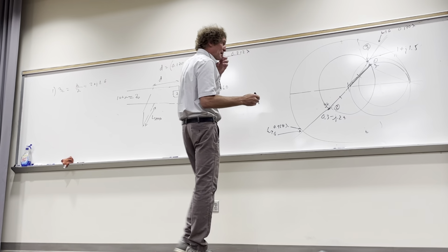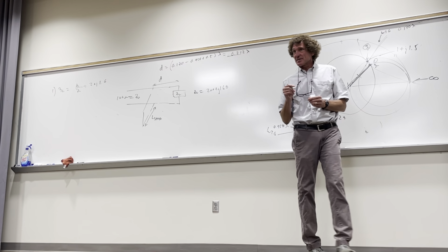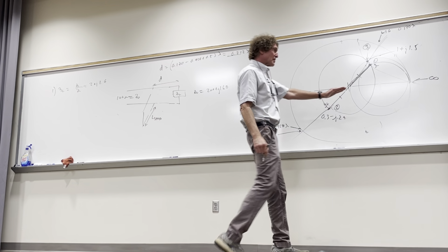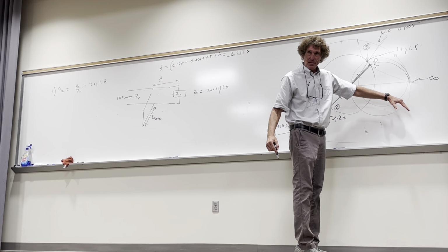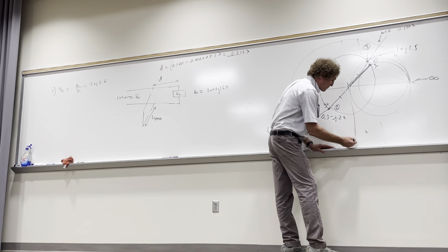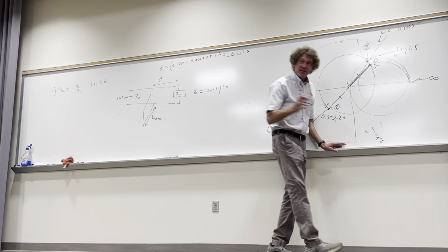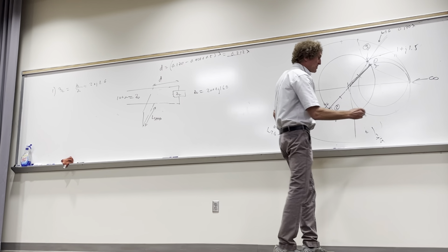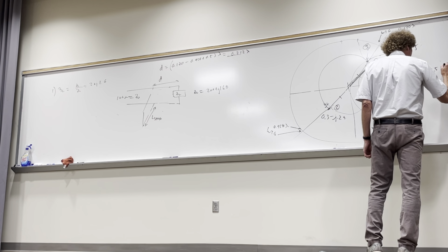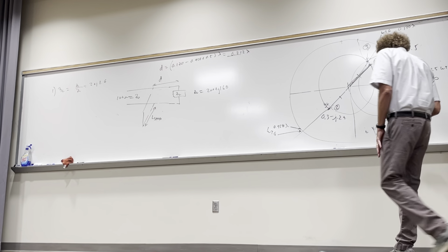So in a Smith chart, where do we come in? We come in right here, that's infinite. Now what do we have to move to? All these values below the equator, down here, are negative J that we're gonna hit. We need to move to negative J 1.5. And negative J1 is about there, so I'm guessing minus J 1.5 is about here. So now we have to figure out the distance from here to here. This has a mile marker of 0.25 wavelengths towards generator. What's that mile marker? That's 0.354 lambda.